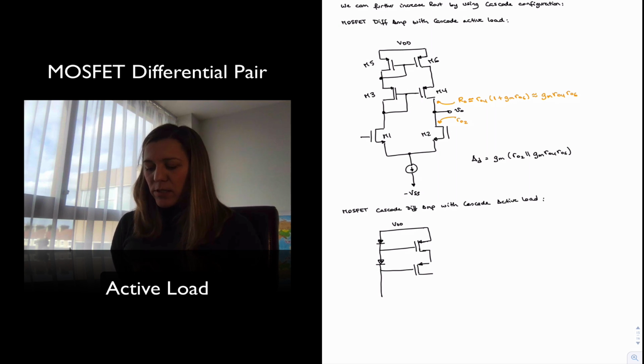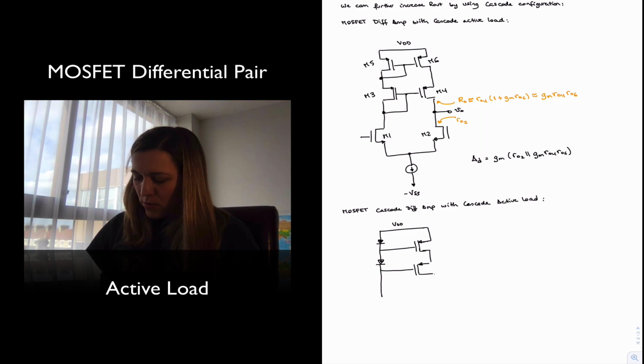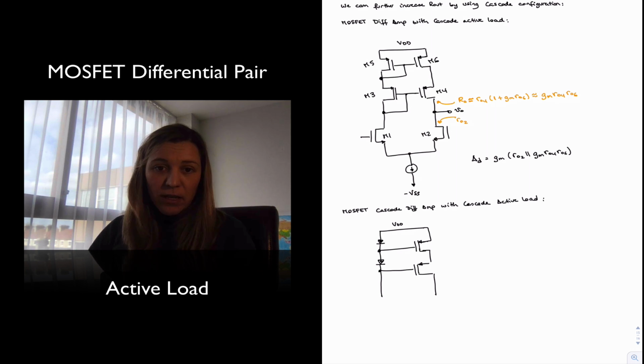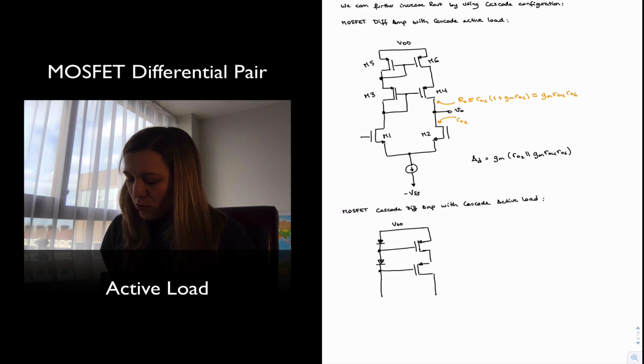All right, so notice that those are still the same because, again, the drain of M5 is connected to the gate of M6, and so those are the connections that we have here, essentially. These are still diode-connected transistors, so if you go inside the circuit, this will be a transistor connected in that fashion of connecting the gate to the drain. And then we will have two NMOS transistors.